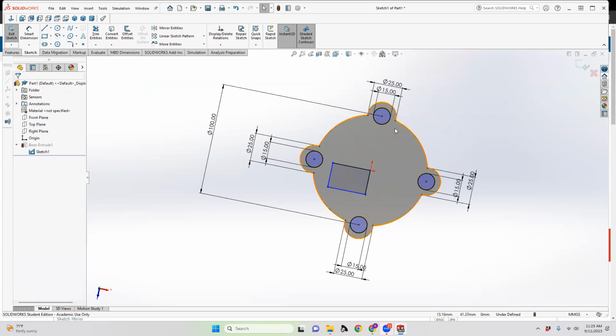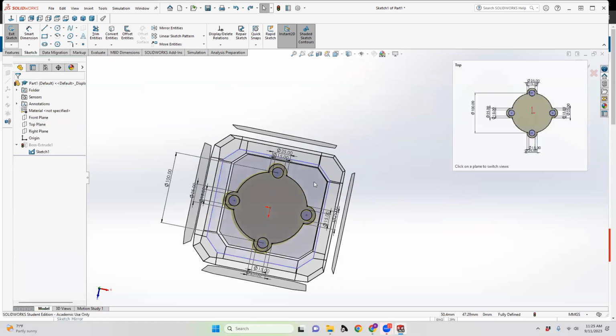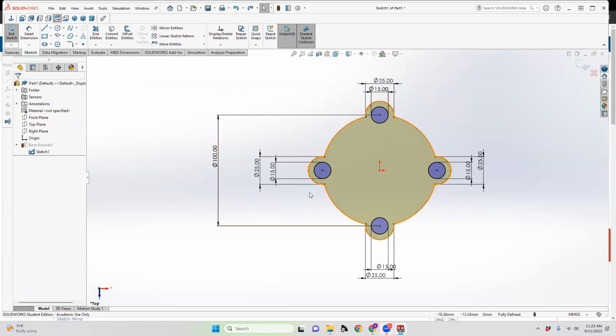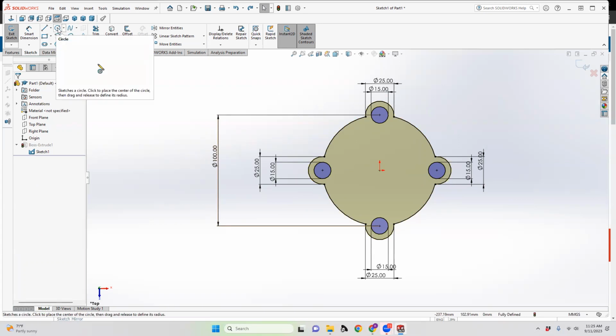So that's why I recommend always come back to reset your sketch to be square with relation to the origin, so that you're going to save yourself seconds and minutes on each of the sketches that you're working on, because over time, all of those little details are going to be kind of a pain.